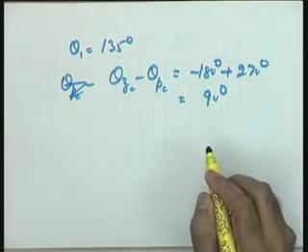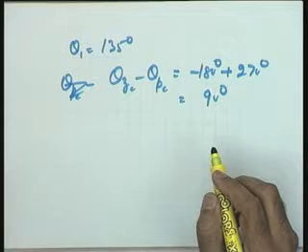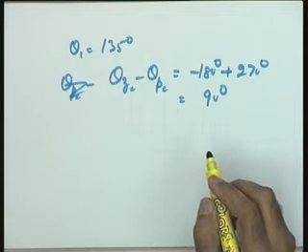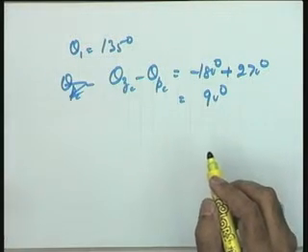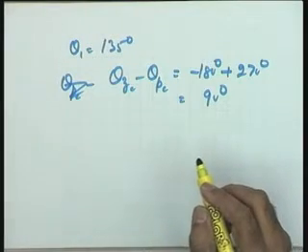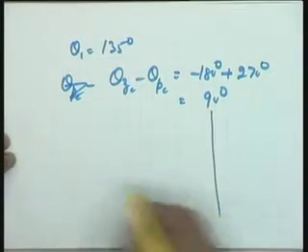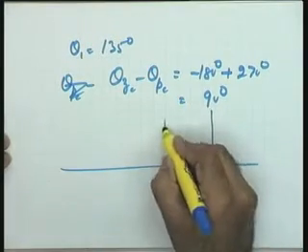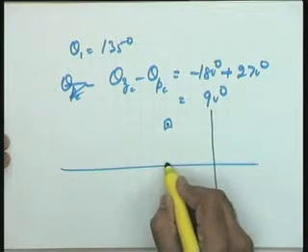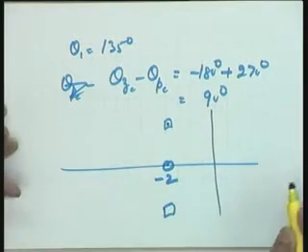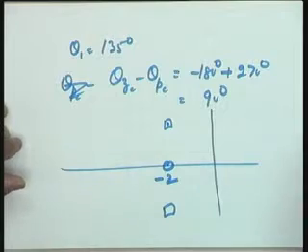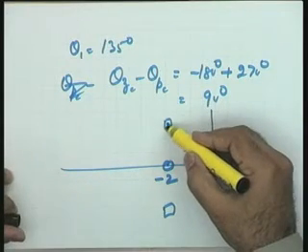Now if this 90 degrees is to be realized by a suitable pole-zero pair, you give me the location of one. Now the point comes: where do I place the zero, for example? Pole location will automatically follow. Let me say, with the arguments to follow later, I place the zero at minus 2. The reasons to follow.